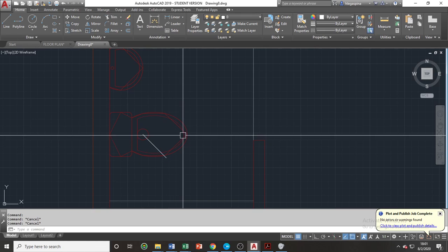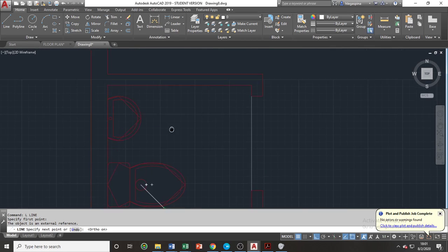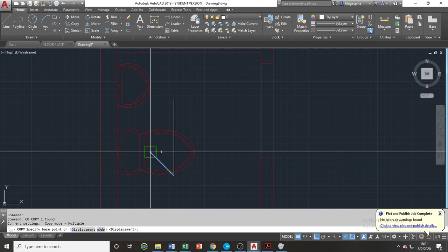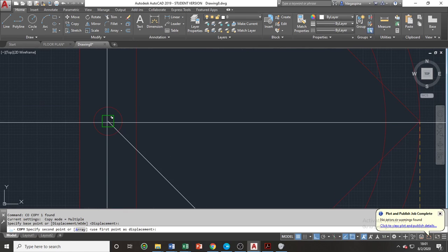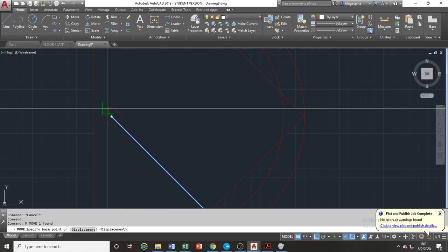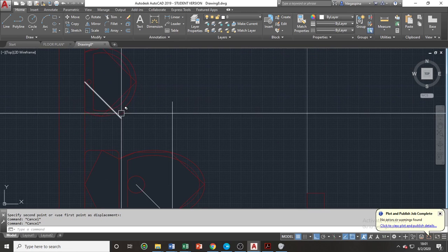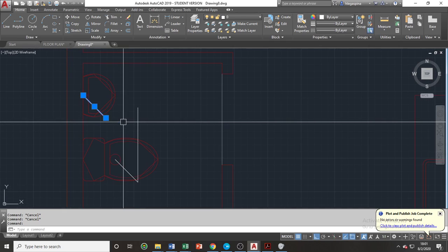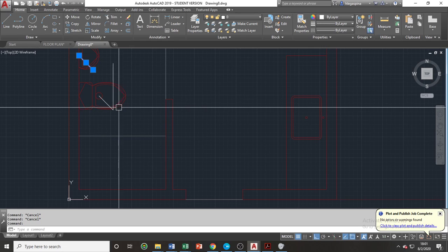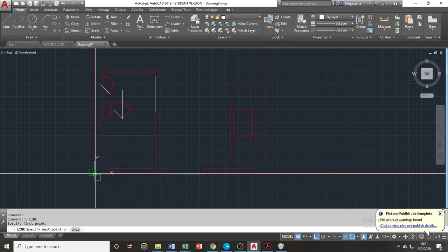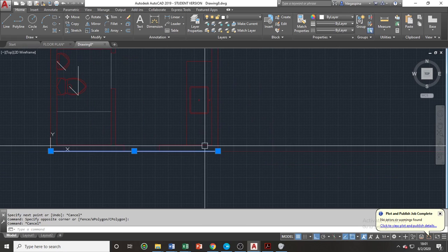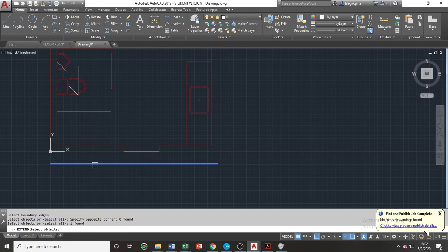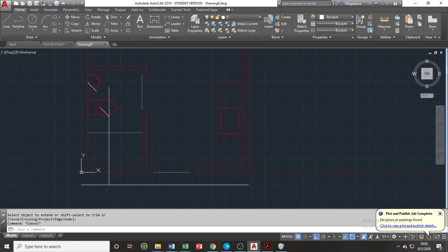So the rule in sanitary layout, as you've learned in your building utilities, is that your plumbing systems for sanitary should have a layout of 45 degrees, which connects the branches to the main branch of your sanitary pipes. The main pipe should be 1 foot away from the wall.